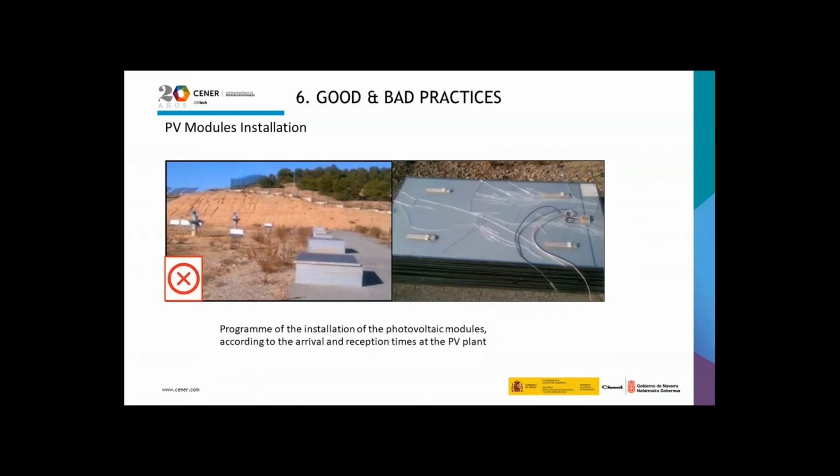The PV modules installation must follow a program of the installation of the photovoltaic modules according to the arrival and reception times at the PV plant. If not, modules can appear in the middle of the PV installation and can suffer these consequences.